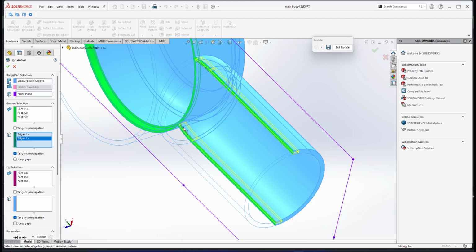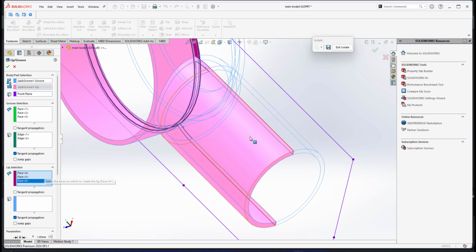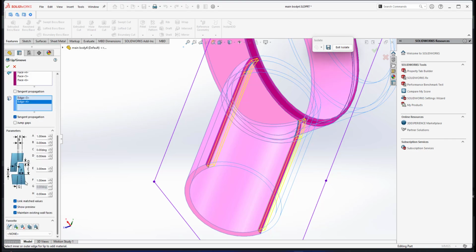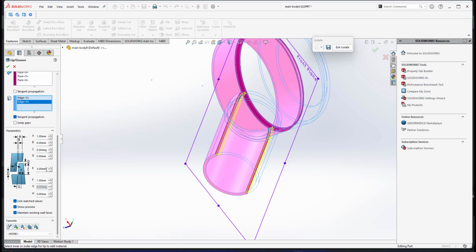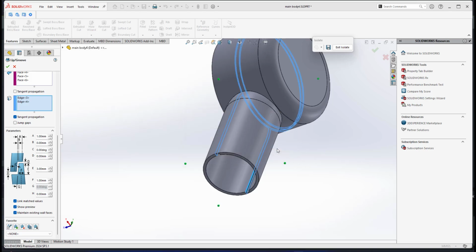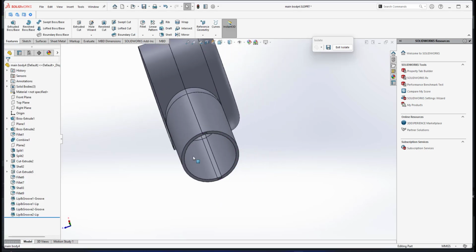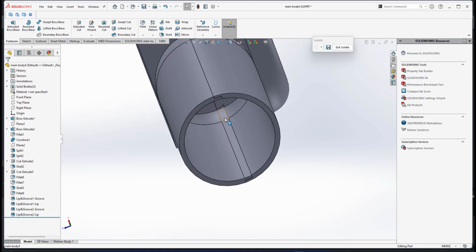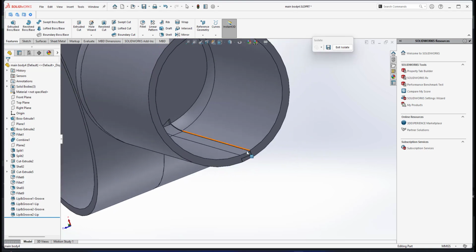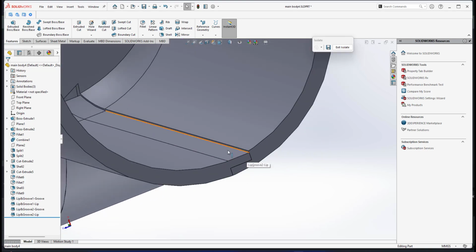This one I want to create the groove. And here the faces to create the lip are already highlighted. Here I select the edges to create the lip, right? The extension of the lip is 3 millimeter, and the cutout of the groove is also 3 millimeter. If I click OK, I just need to show you. Hold on. Okay, I click OK, there will be an error. As you can see the output, the outcome is not right. We have a cutout like this, and also extra edges created. Can you see the result, something is not right.